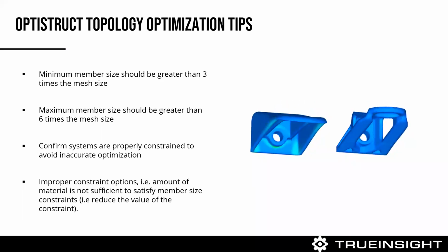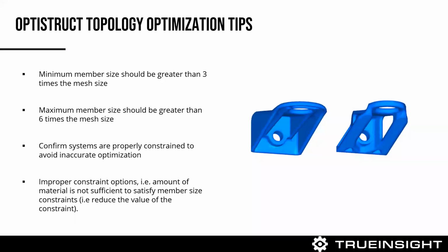The next thing that I run into a lot is, most of the time, optimization is done from an assembly-based level. And when you're dealing with assemblies, you obviously have contacts within OptiStruct. So like your tie contacts, how parts are connected to one another, how they interact. A lot of times you may neglect your contacts.